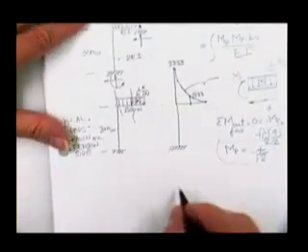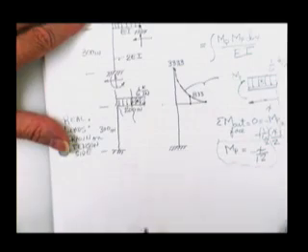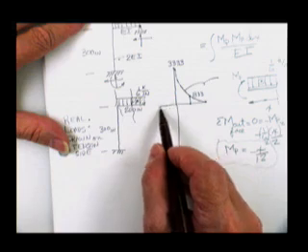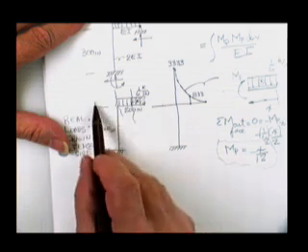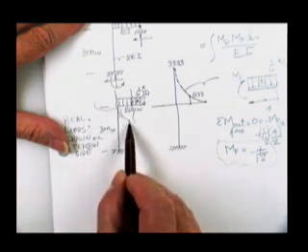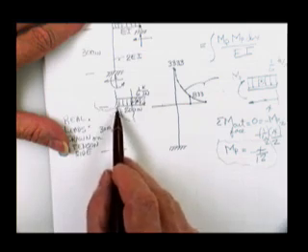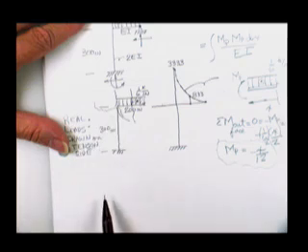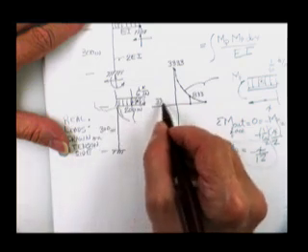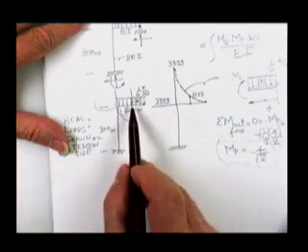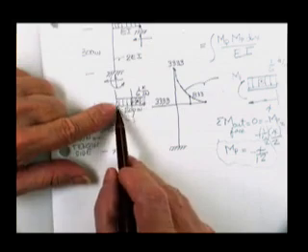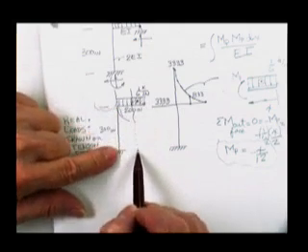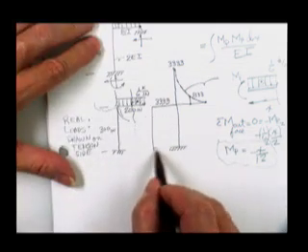Now then, I'm going to show you the moment diagram on the vertical piece. When you turn around a corner like this, the moment's the same on both sides of the corner. You can come on down inside of here and cut. You see you get the same moment in the corner as you did on the other side of the corner. And so it's 33, 33. And the force is 1/6 times 200 multiplied times the moment arm, which is the same all the way down. And so the moment stays the same all the way down.